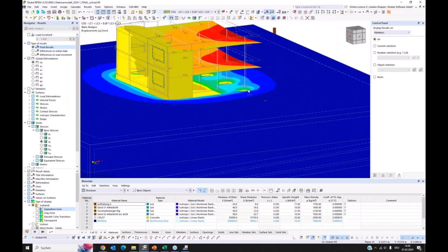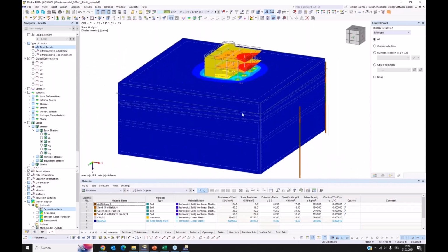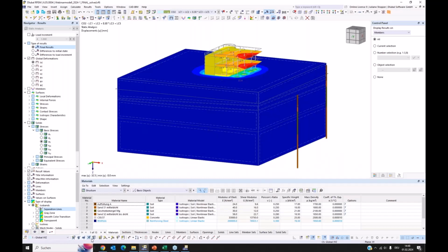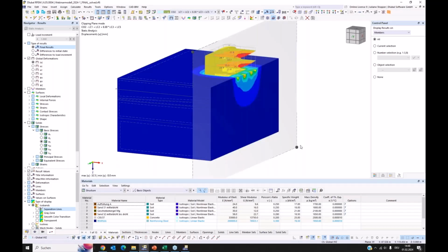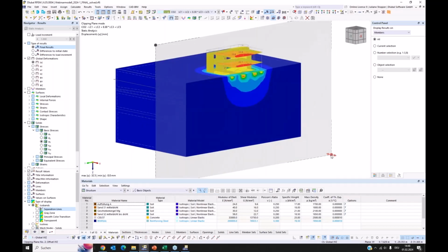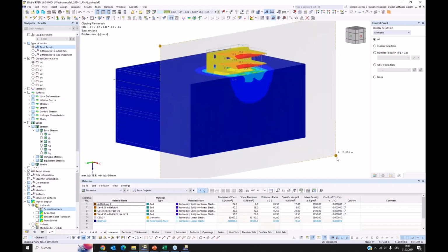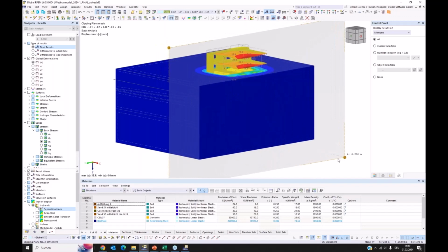And we have a nice feature for having a better look at the inside. We have here at the bottom the menu where you can select the clipping planes, and if you just click it, you get a clipping plane provided, and you can pick one of these 4 balls and you can move it through your 3D body and have a look inside.